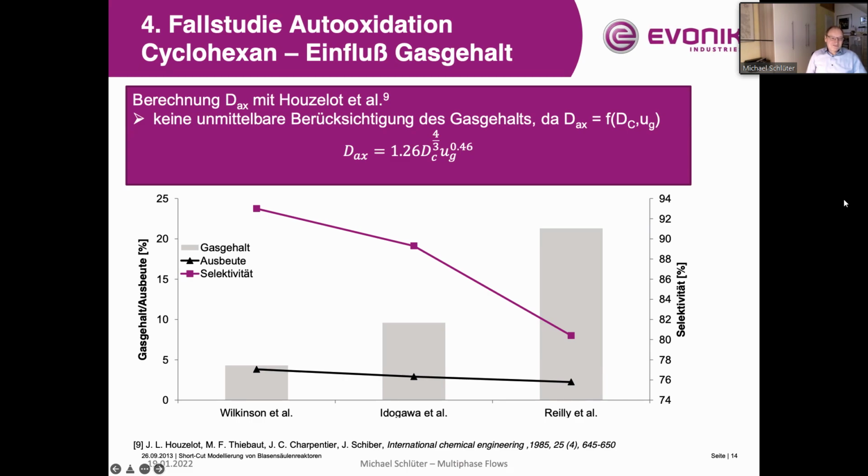Okay, but on the other hand, don't forget 4 times higher volume means 4 times more energy to drive the system, 4 times more educts that you have to feed into the system, more energy that is necessary to clean the product afterwards, to purify it, for example, by thermal processes like distillation or something like that. So you can be sure that your process will be much more inefficient if it's scaled too large.